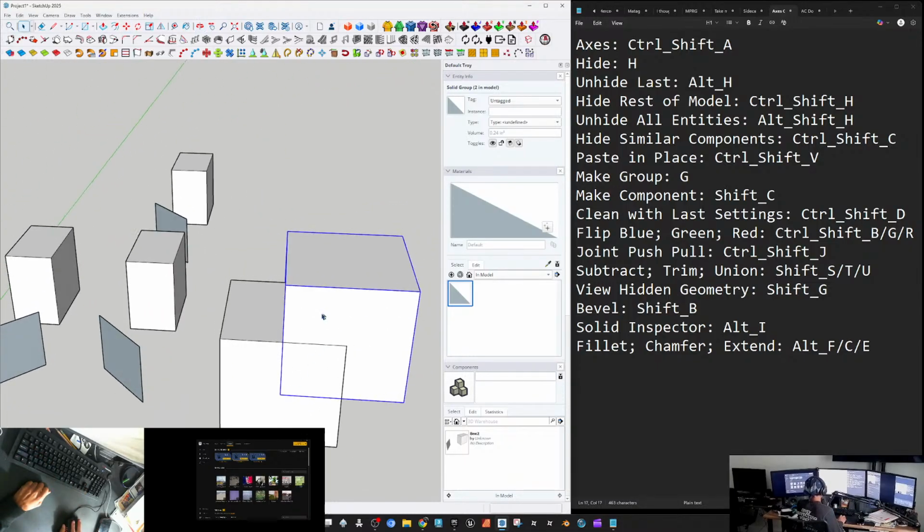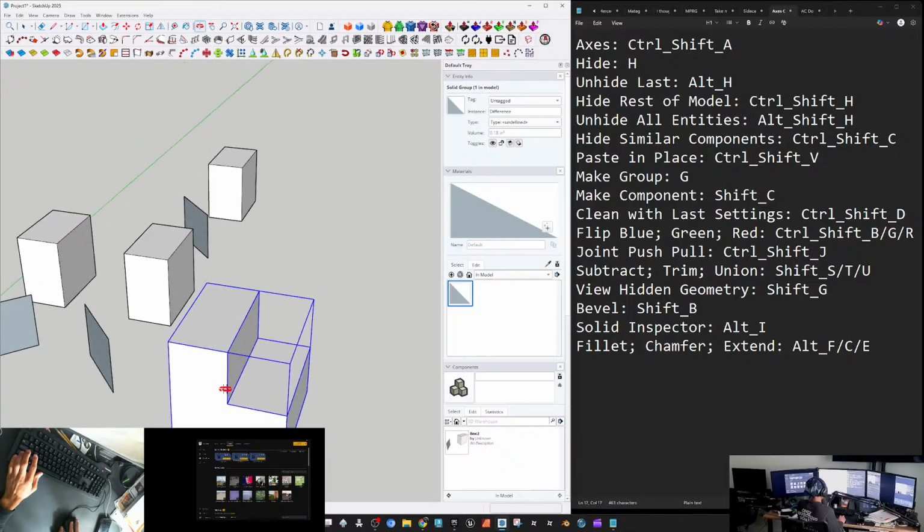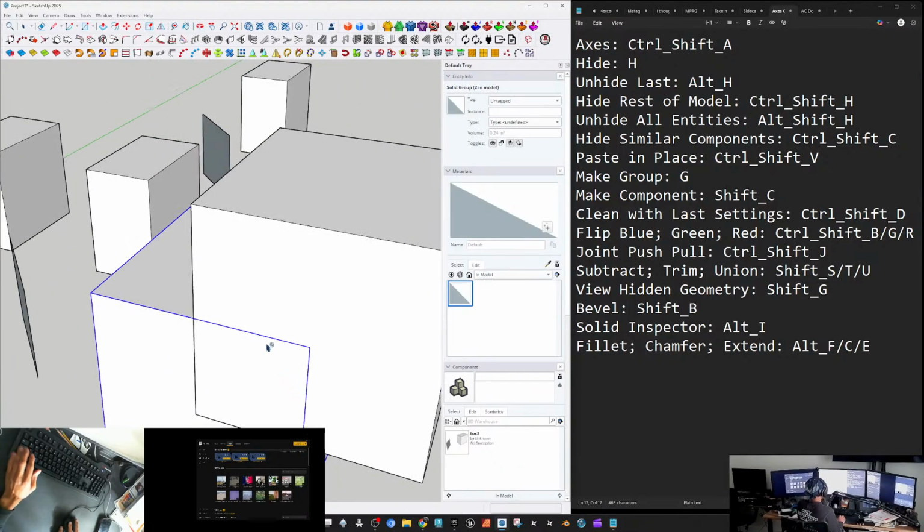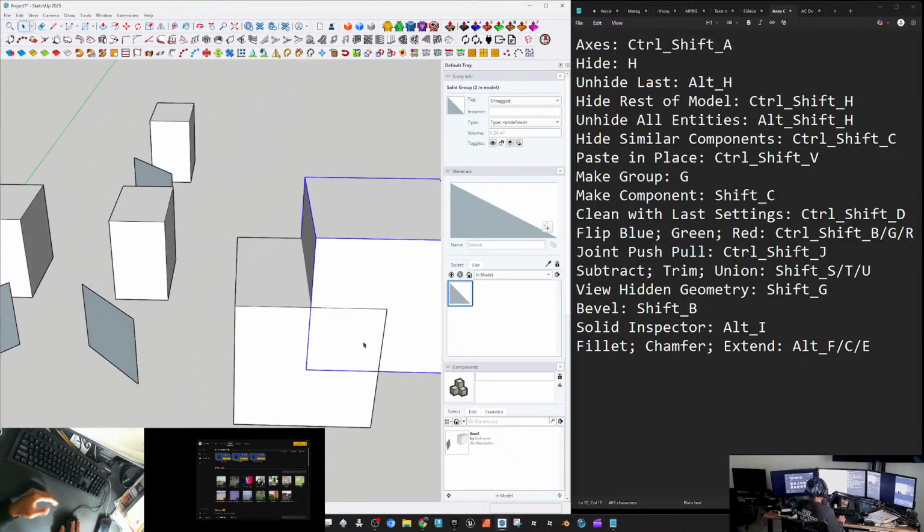And let's say I want to cut this box out. I should be able to select, I believe it's the first object, then the second object. And with the shortcut that I created, I have the option to do a subtract by pressing Shift S. Let's see if it's Control Shift S. Nope, just Shift S. Okay. So now the first object you select is the object that will be used to do the subtraction. Grab the second object with Shift and click, Shift S.